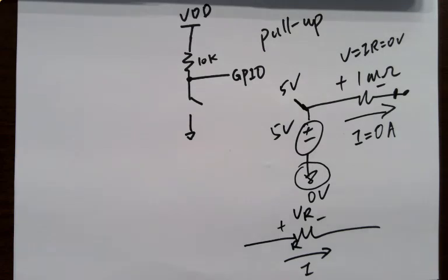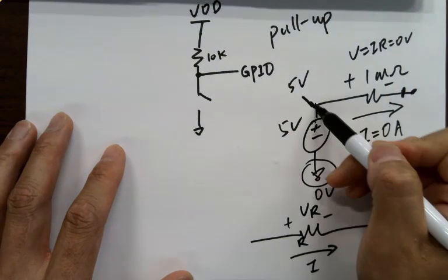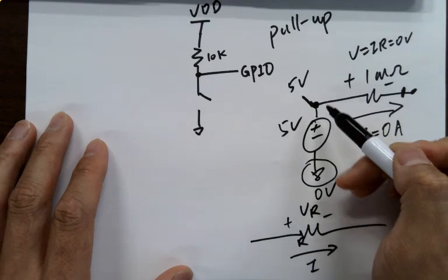Because all the voltages are relative. They are just differences, subtraction of 2 points, one subtracting another. You define the reference point using the ground symbol. So that's why I can say the voltage at this point is 5 volts, because I'm comparing this point to 0.